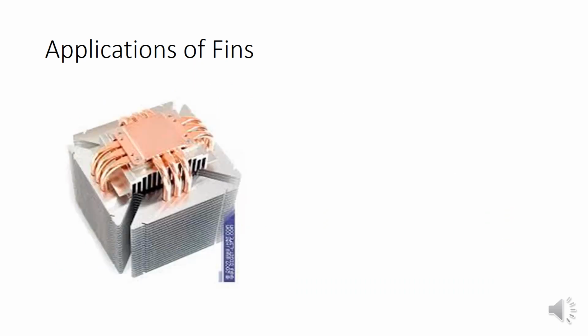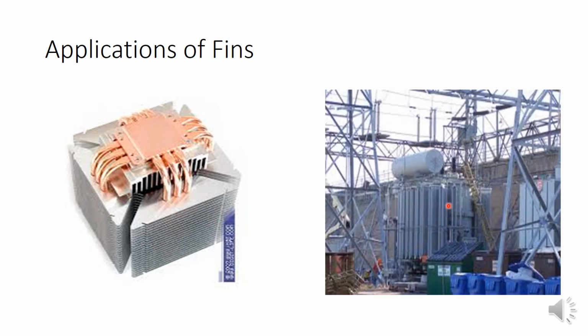And these fins are not only applied in engine, they are applied in every field. We can see this is a computer processor cooling system. We can see inside it a number of fins made of aluminum alloy or aluminum. Here also it increases the heat transfer by convection by increasing the area. And we can see they are applied also in transformers. So fins are used in every system, mechanical, electrical or electronic system, for increasing the heat transfer by convection. They are simply increasing the surface area of the system.